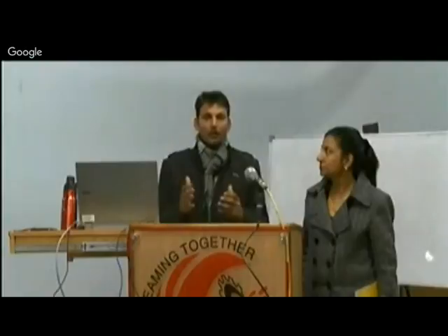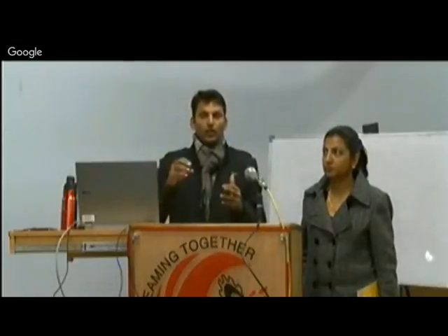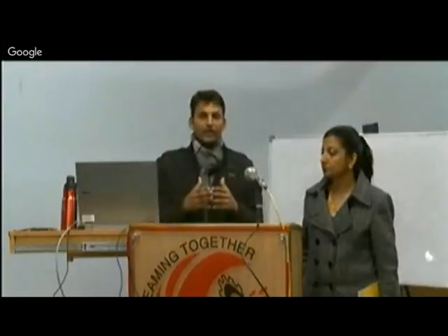Although now we are also working on non-contact type. The contact type sensor that we use basically worked on the Wenner array and Schlumberger array principles, which actually use the impedance or resistance measurements of the fields, and relate them to the soil composition: sand, silt and clay, water holding capacity, nutrient holding capacity. So those different array principles, we made into a specially designed array.